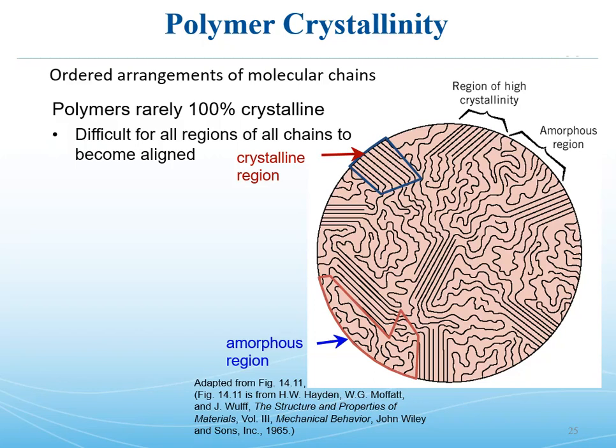And so we'll get into that a little bit more with mechanical properties of polymers and looking at how a crystalline thermoplastic might deform when it's subjected to uniaxial tensile stress. And those will have very specific regions of output on a stress strain plot, which you can measure.